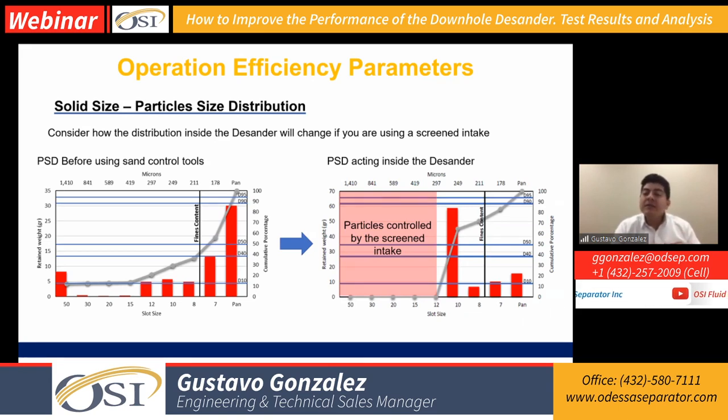A rod pump is designed to deal with a small portion of the sand. The problem becomes, and the reason that we get some plunger wear, is because we're allowing all the sand to go through at the same time. That's the issue. In this case, we got a high runtime, and regardless that we shifted this, we didn't see any severe marks around my plunger, and I was giving the opportunity to my pump to deal with these finer particles.